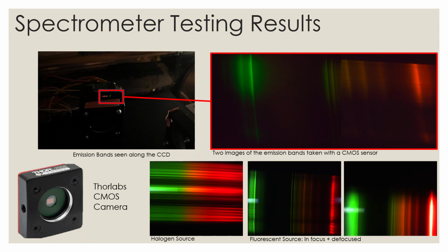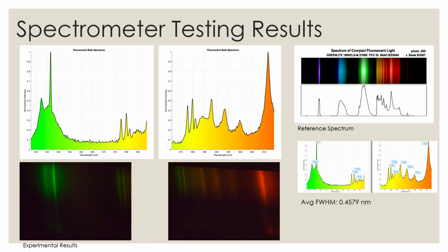While we do expect different results when our system is interfaced with the CCD, this testing offered a sanity check. Using MATLAB, images from the CMOS sensor were processed and calibrated by manually matching the most intense peaks from a fluorescent reference spectrum to the image.